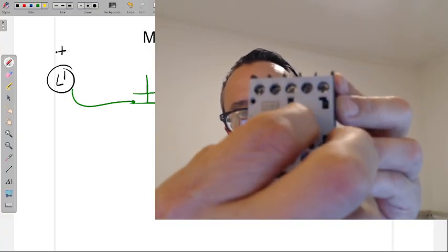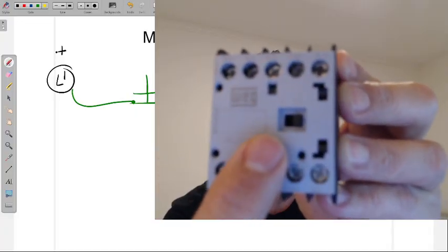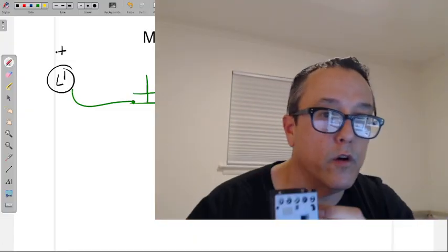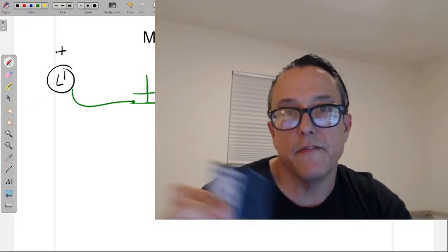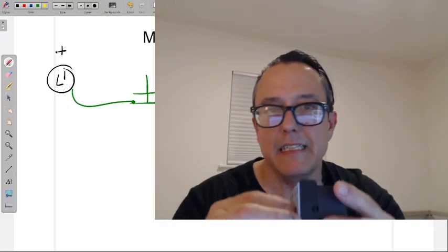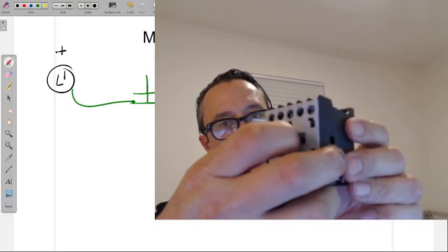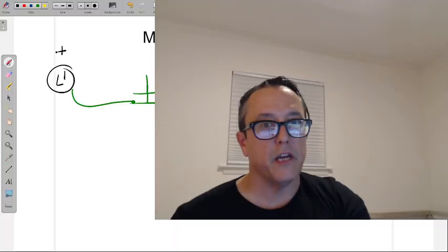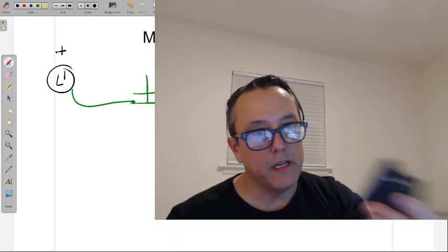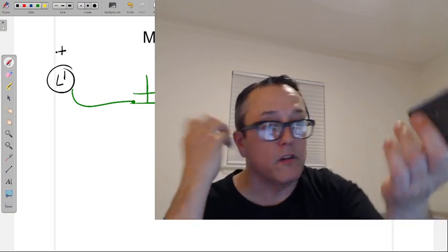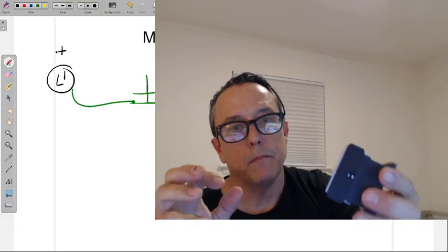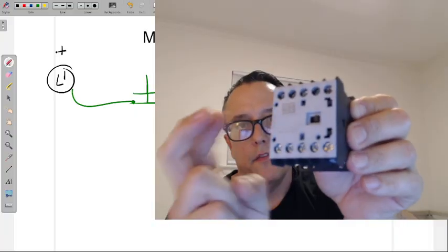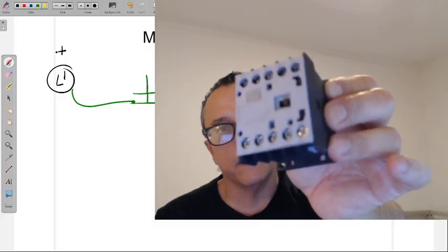All contactors have a manual, all right? It has an ability to manually close those contacts in the event that your coil goes bad and you want to just see if systems are still operational. It is not recommended to just force that closed. You will start the motor, and if there's a problem on the motor or if there's something jammed up in the machine, you can damage things a lot more than that, and even hurt somebody, you know. But that's essentially what happens when that internal coil gets magnetized. That's the way I just forced this contact closed.